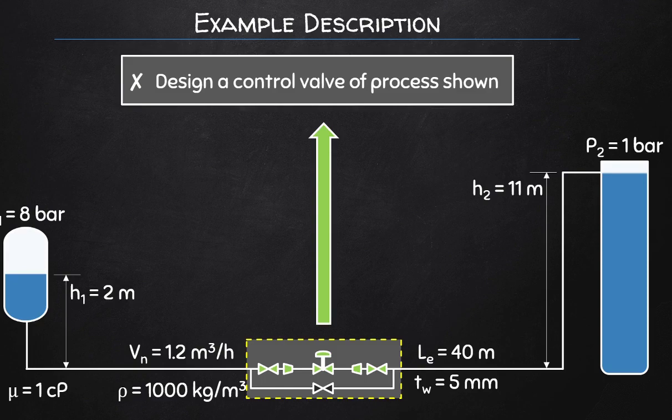So 1 millimeter plus 3 or 4 millimeter will give us 5 millimeter. Generally it depends on the process. The corrosion factor is really going to be quite substantial, so between 3 and 4 millimeter. So let's just say that we've rounded the calculation for the wall thickness to be 5 millimeter.